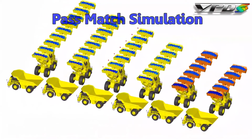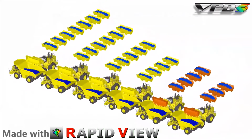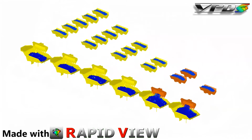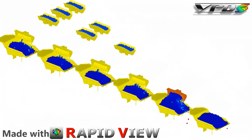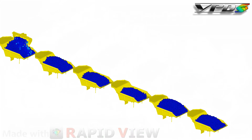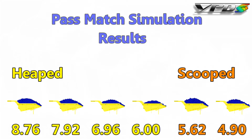As the loaders begin to move the material in the simulation, you'll see colors changing, which represents the speed of the particles. And as each consecutive bucket comes in and dumps its load into the dump body, the material begins to settle into the pile. And as the dump body begins to fill up, you'll see material flowing over the side walls and off of the tail of the dump body until the final load is settled. And we use this final load that's settled in the dump body to calculate the pass-match ratio.